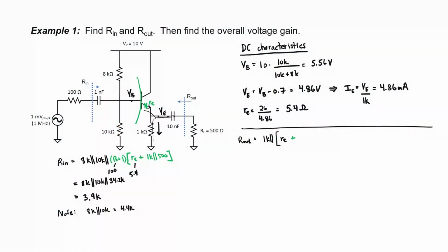We can use it for both the input impedance and the output impedance, but we can't use impedance reflection to find the gain in both places. We can use it for either the input impedance or the output impedance if we're only looking at one of those at a time. Looking back from the base here, we have 3 resistors, 10 kilo ohms, 100 ohms, and 8 kilo ohms.